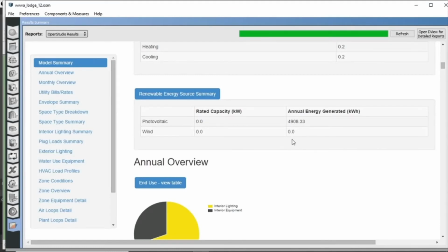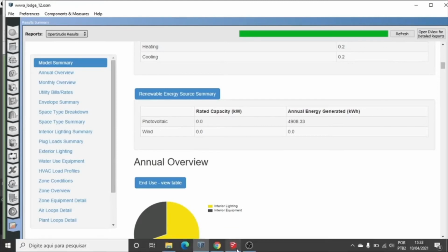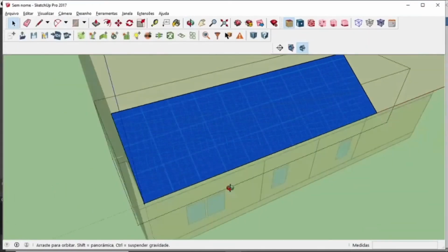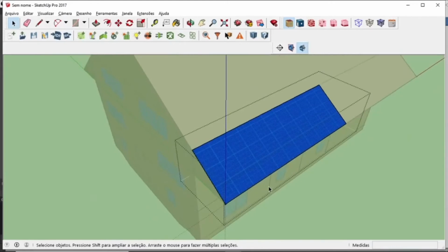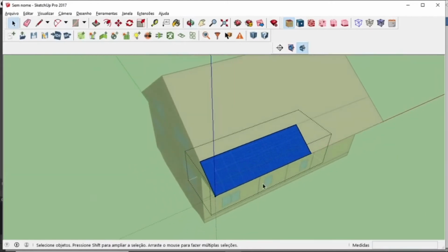We will now work with efficiency. By default, the program uses 20% efficiency. We're going to increase the efficiencies to obtain new values of electric energy. Again, we are going to edit. Every time you edit, you need to click on the surface and remove the existing system as we did previously. It allows you to deploy a new system.